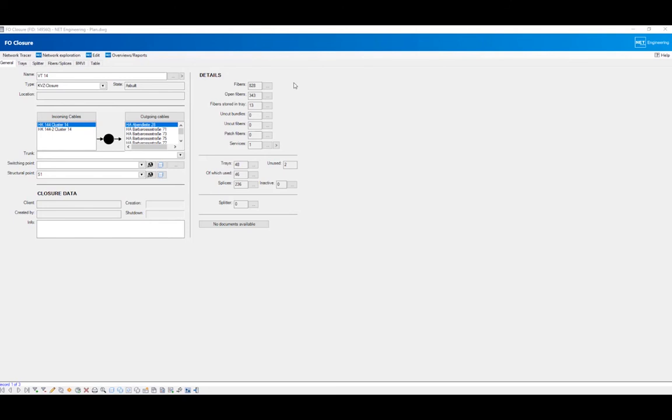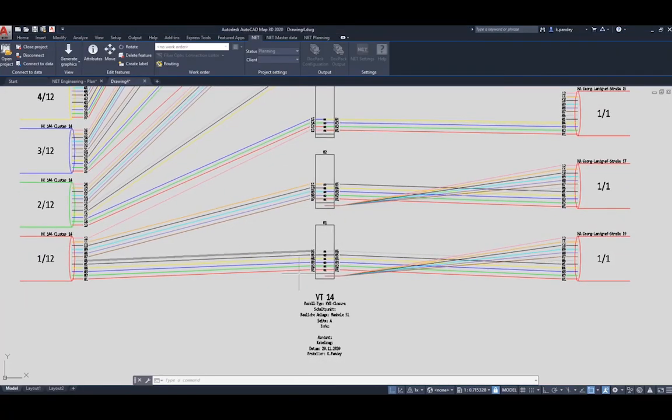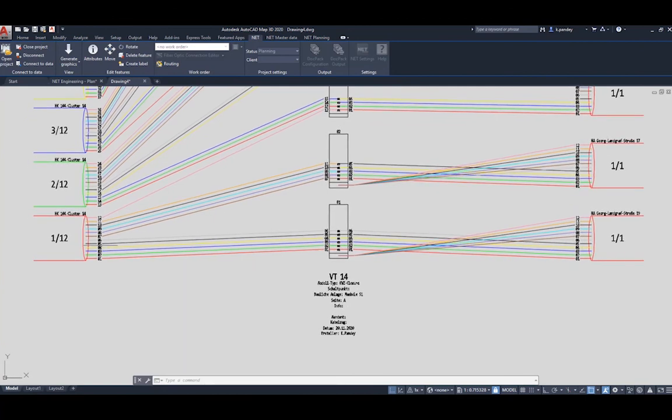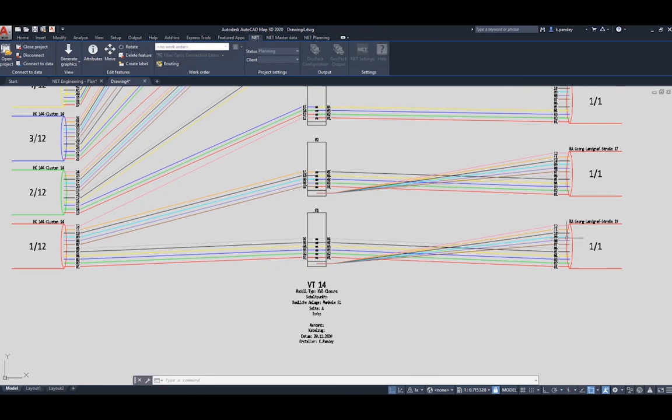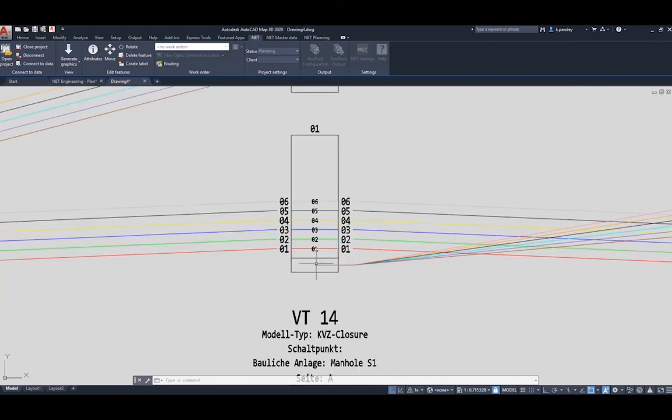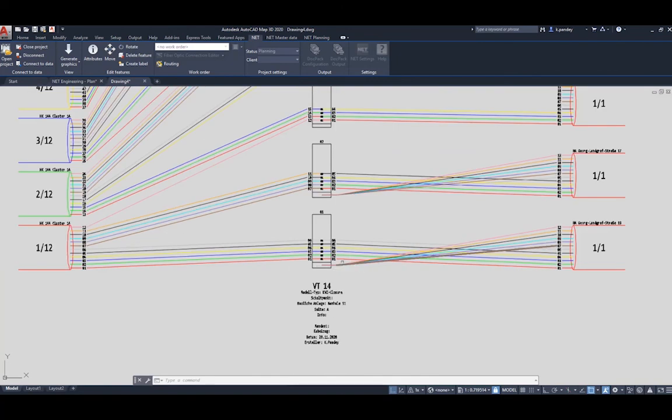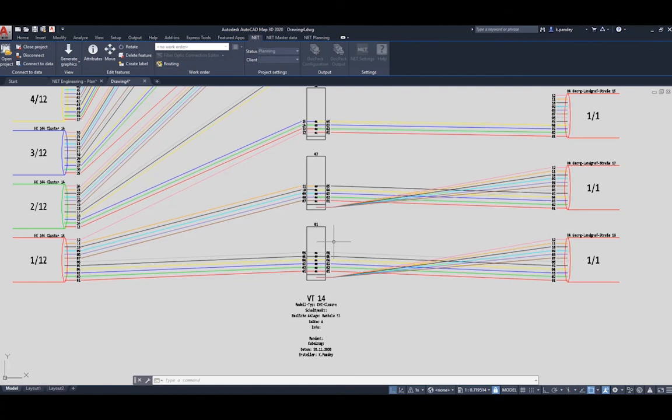When the fiber connection is made in the fiber optic closure, I would of course like to get a quick overview of the corresponding connection, and they are both available in graphical and tabular overviews. So let's take a look at the graphical overview. It gives the representation on the fiber level, where you can see the incoming feeder is spliced to the outgoing endpoints of the house connections, and the remaining fibers have been placed in the trays. And the user could edit the information from the fiber connection editor as we did.